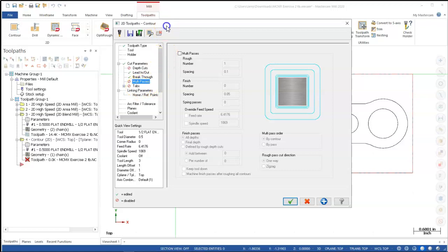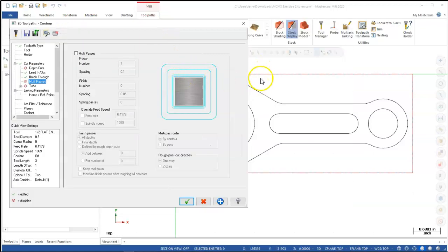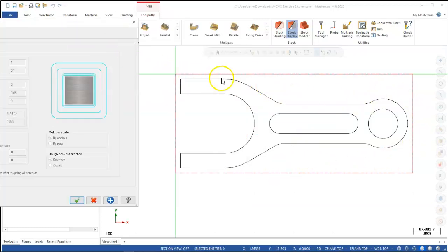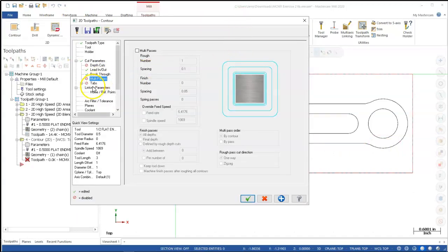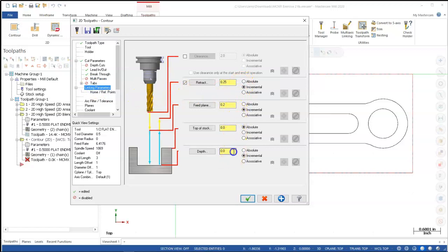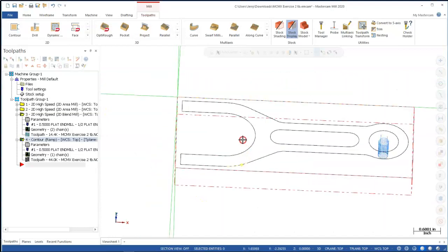So I guess that would be the alternative, if we didn't do the dynamic, which is going to try and minimize the number of passes, we would end up doing a contour that would step in and remove the material. Since there's not a lot over here, we would start out here and then do multiple passes to come around the part. So that would be one for comparison. And then our length, top of stock, and the -0.5. I'll switch back over to the absolutes, and we'll go ahead and take a look.